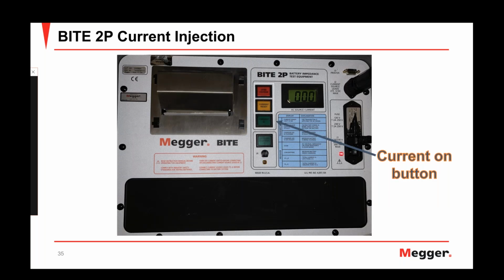What you're going to do is push that green current on button, and it's going to illuminate green. As the capacitors in the unit warm up, and we wait on that process, the yellow current ready light is going to come on. Whenever we have a current that's being injected by the unit, we're going to see 11 amps on the ammeter on the transmitter.